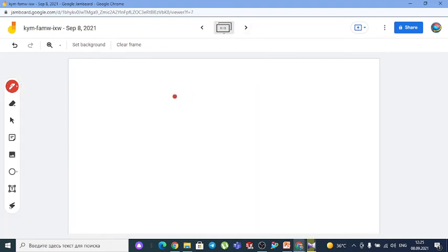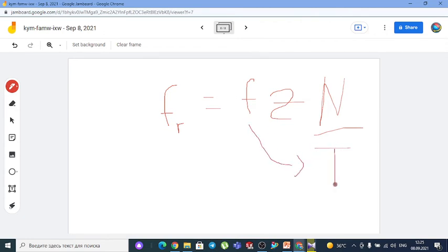So the next value is the feed rate. The feed rate is equal to the feed times Z times N. N is what we calculated for the spindle rotation. Feed is taken from the table, and it relates to the material of the workpiece. Z is equal to which value? I already explained it. Yes, correct.